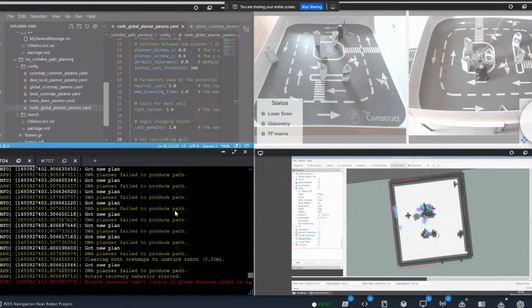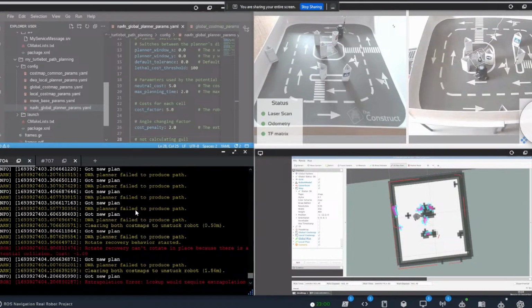This is fine, the DWA. That's related to differential drive robots, and this is a differential drive robot. There's another one called TEB, which is for car-like movements, which actually was my first guess because it was sort of backing up, and I haven't really seen a differential robot do this with move base. Usually what differential drive robots do is they just spin on themselves until they can have the plan. Since this path is like a straight shot every time, of course it's going to have to move back and replan.